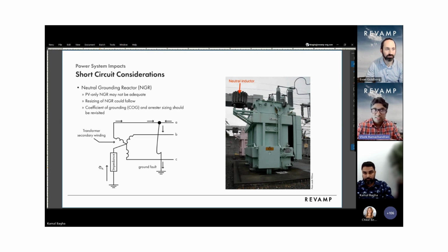Also, the addition of the BESS to a previously existing PV system means the BESS facility is now going to inject some additional fault currents into the PV system when there are abnormal conditions. Putting it in numbers, for the PV system, the fault current observed was 20 kiloamps prior to the BESS. Now, with the addition of the BESS, it's gone up to 22 kiloamps or so. So there's an increment there that needs to get accounted for in these short circuit calculations.